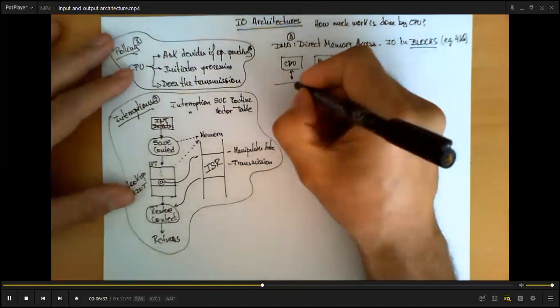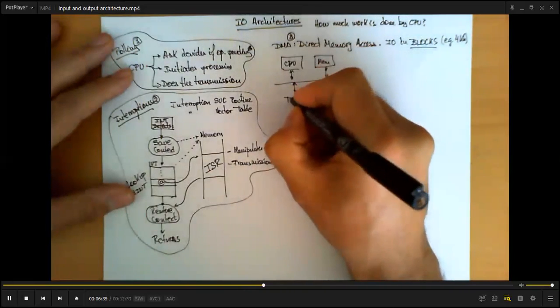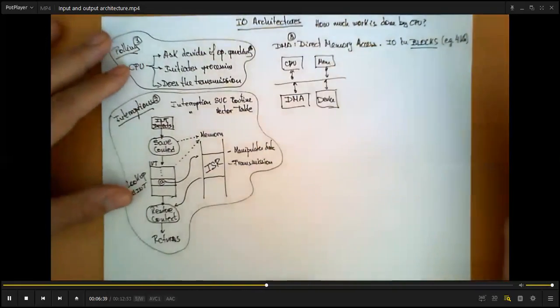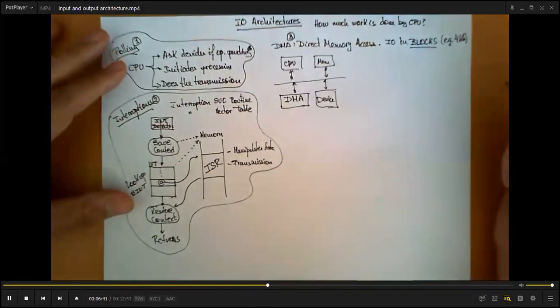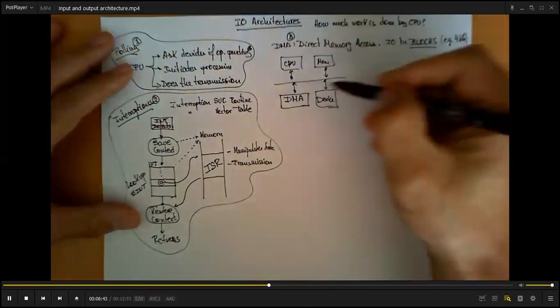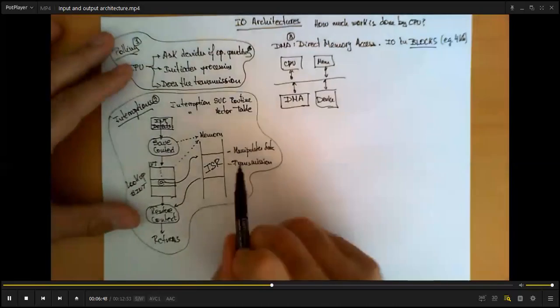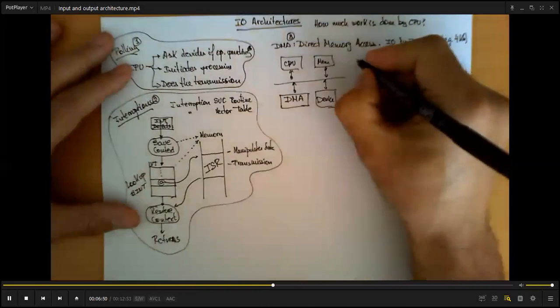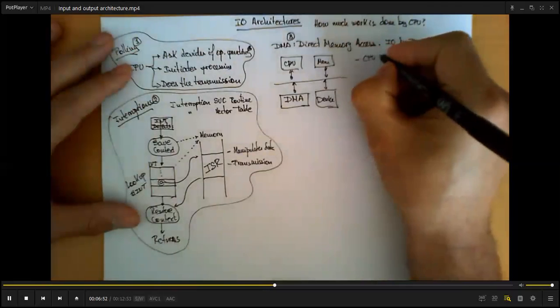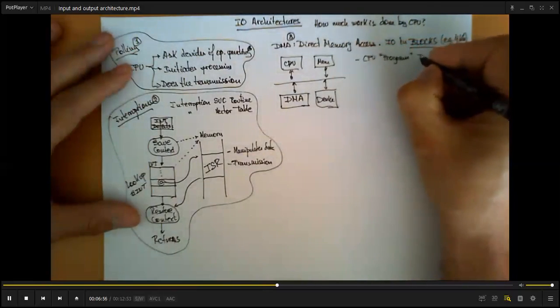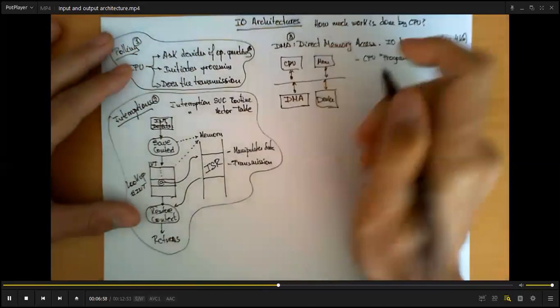The solution adopted by designers is this strategy called DMA, by which a new circuit appears here. This circuit is called DMA. Now the DMA is hooked to the bus, or connected to the system, to remove the responsibility of making this transmission from the CPU. So what the CPU now has to do is program the DMA operation. So it tells the circuit 3 things.